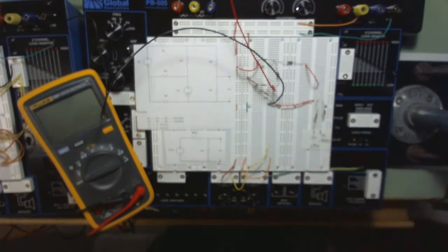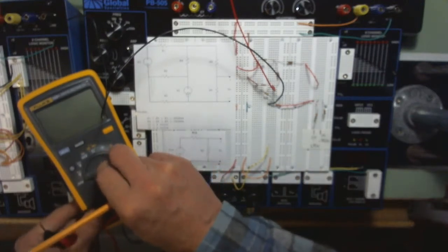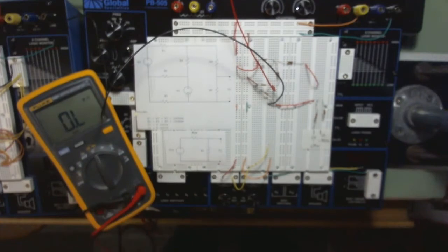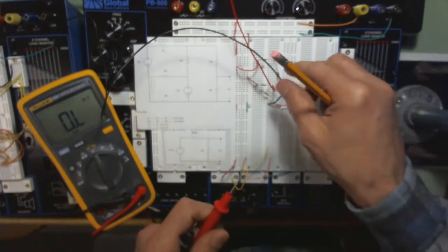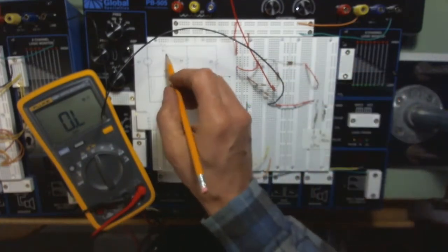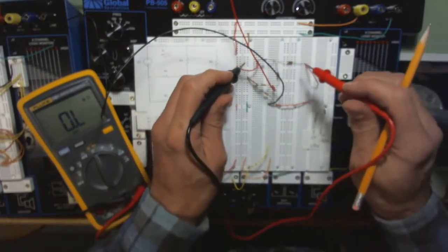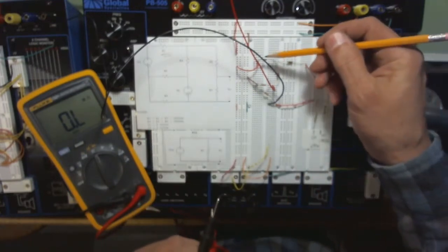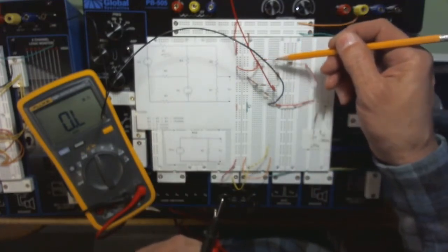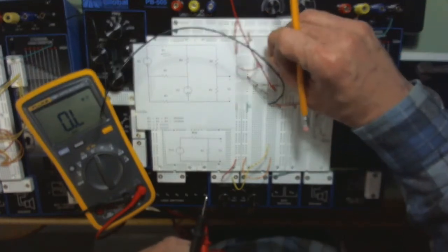So in past labs, I spent quite a bit of time talking about measuring resistance and whatnot. I've measured the resistance already. These are well within spec. The only thing I might say is, one, we want to measure the resistance with the voltage off. The voltage is off on this thing. And if I try, for instance, on this R1 right here, to measure the resistance of this thing, I'm going to get the resistance of the entire circuit, which is not what I want. So I want to unhook at least one end of it.